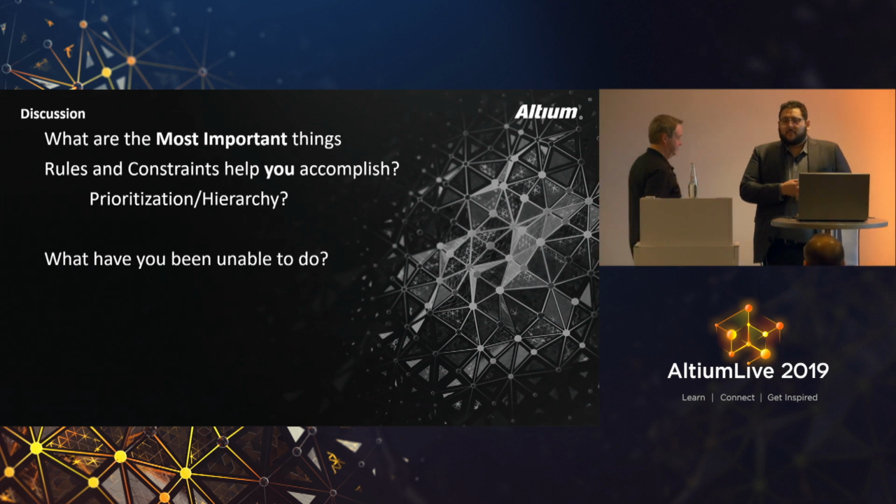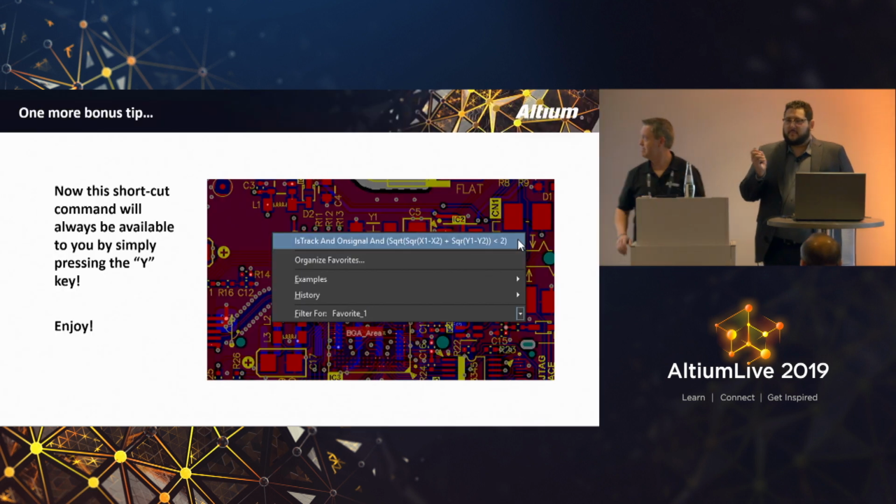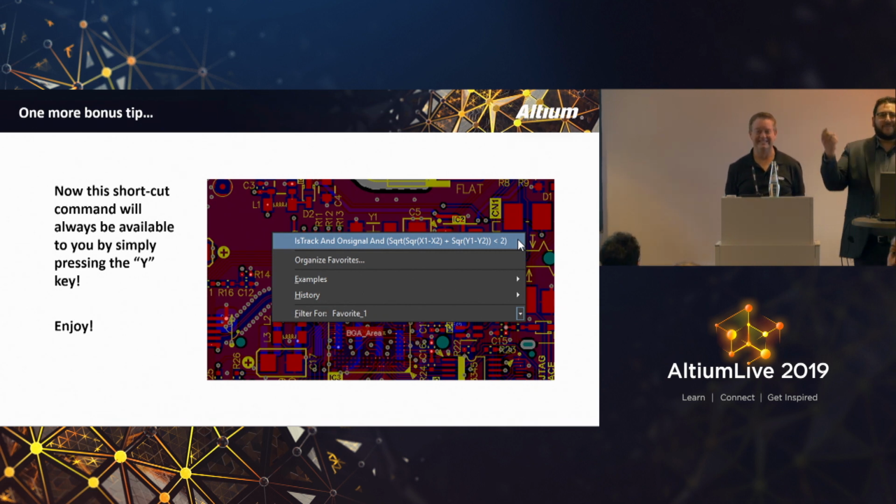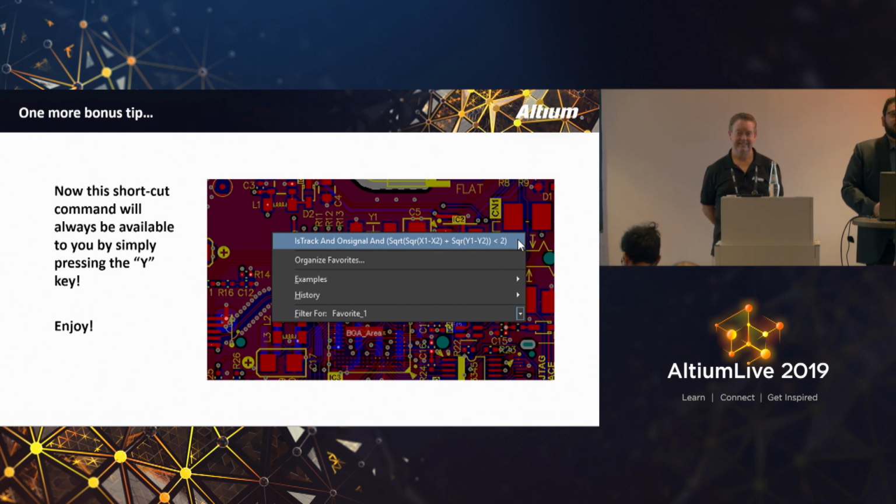Could you go back one slide, just before? For this calculation, there is a function inside Altium. It's called trace length. It's not well documented, but there is in AD17. And you can use that one, and it's a little bit faster.